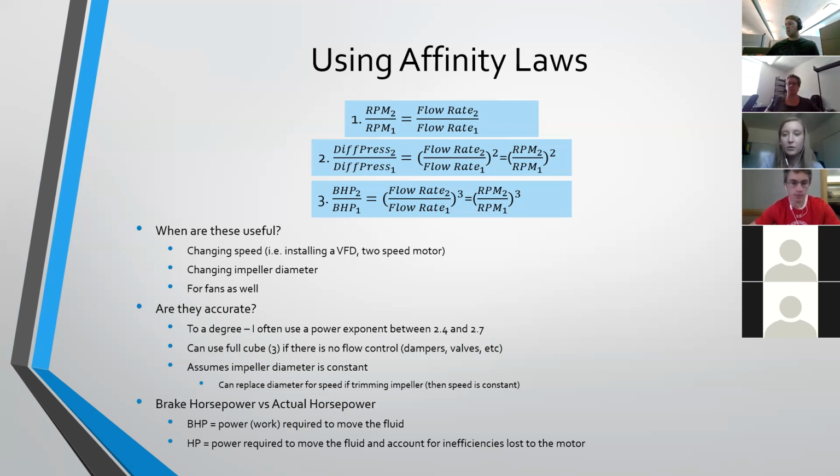Yeah, for sure. I do have a bullet point there on that. The power exponent of the cube is only accurate if there's no flow control. If you have absolutely no flow control, no dampers, no valves, etc., then the cube is what real life looks like.